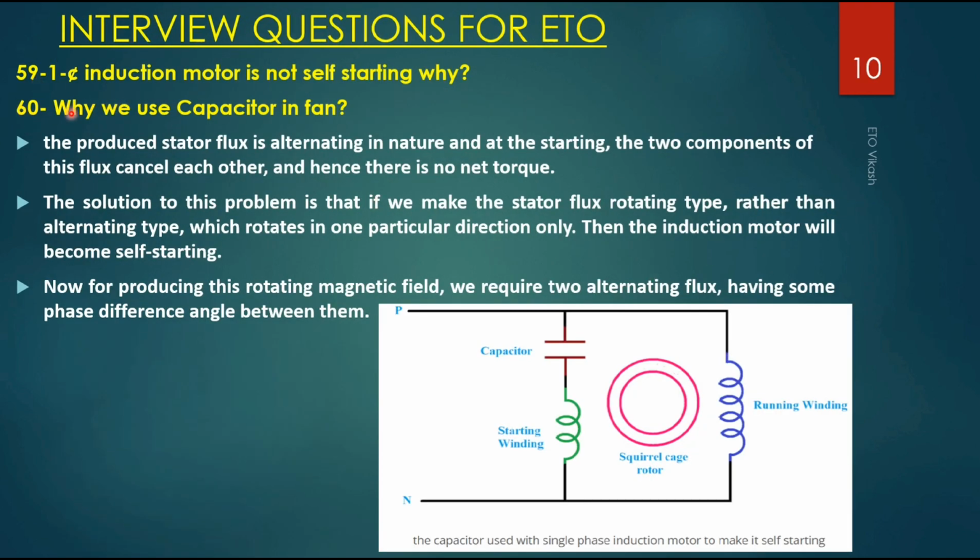Now our next question, 59 and 60, we can explain almost together. A single phase induction motor is not self starting. Why, and why do they use a capacitor in the fan? Yes, a single phase electric motor is not self starting. This is a squirrel cage single phase induction motor, and in it there is a starting winding and a running winding, and on your home ceiling fan a capacitor will be connected.